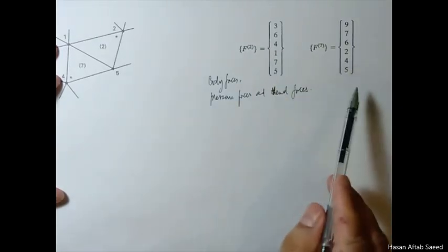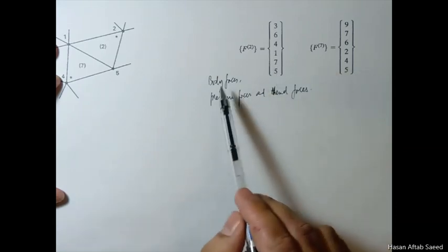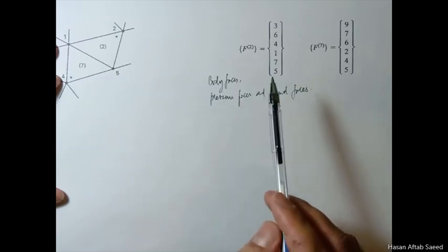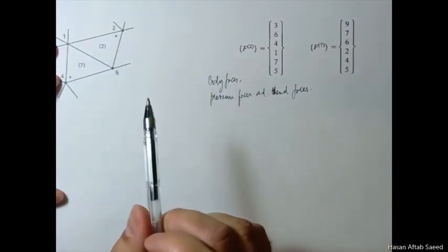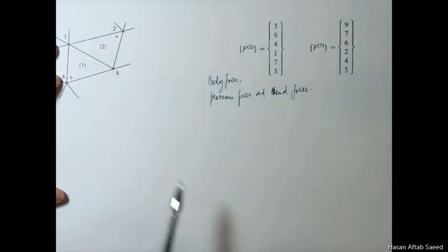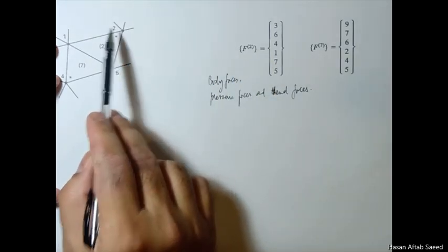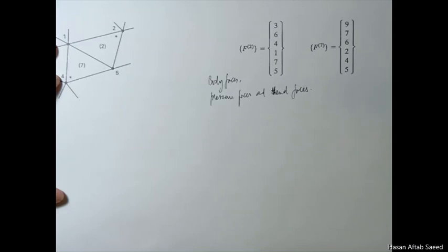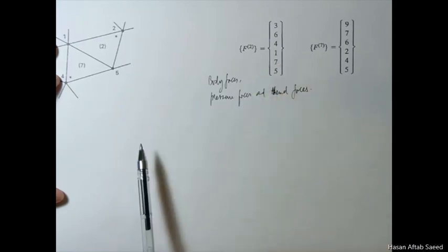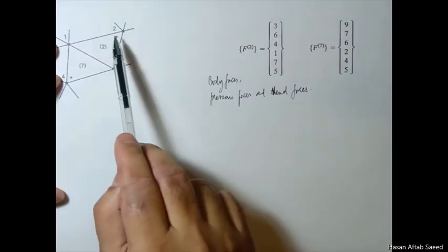First we make the elemental matrices, then we assemble them, and we are going to do that. And finally at the very end, when you have the system F matrix after assembly, you just add at the relevant degree of freedom some concentrated force if it is applied. Because if you apply some concentrated force at this stage, for example element 2 corresponds to degrees of freedom 3 and 4. So if you apply it on the 3 or 4 degree of freedom here, and there is another element here, then again for that element you will also apply it there.